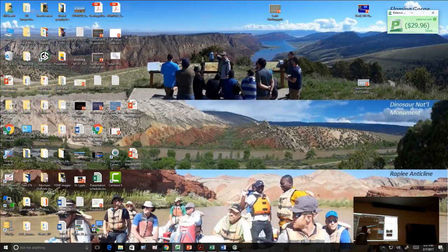If you want to speed up the zoom, just bring your cursor up to this little icon at the top, the compass. Right-click on it and say Zoom Sensitivity. Right now it's set really low. See, it moves much faster.